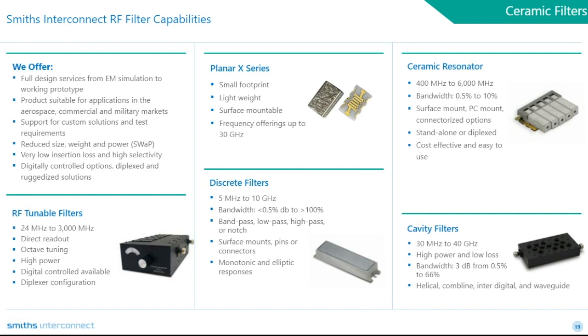And so where you use a discrete, you can have a stock housing and pins and such, but you still have to build the circuit, and there's a lot more detail that goes into generally most discrete circuits. Whereas with a cavity, you not only need the CAD time and you have to machine the metal and form it around it, the ceramics are usually put together. The work is really just done at the design stage, and the assembly follows the same one. So of the topologies, it lends itself to be one of the quickest lead times.